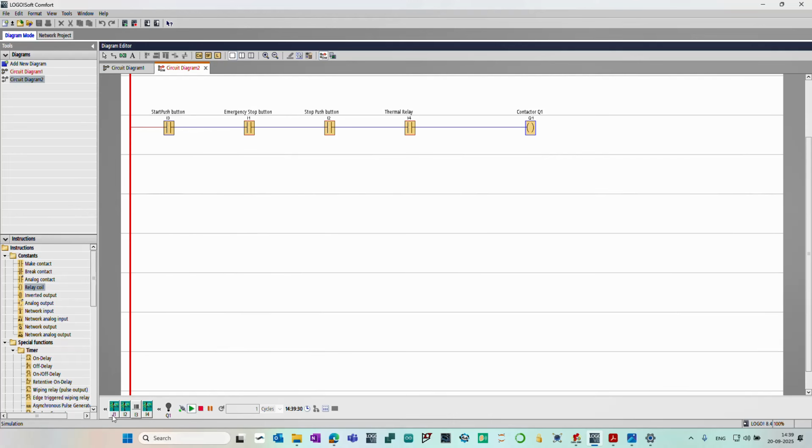If you see here I1, I2, or I4, they are normally closed contacts, and I have put them on the break, momentary break. So when I press them, it should break my contacts, or break all my wiring, the electricity through the wire. Only I3 is normally open momentary, so it will basically make my contact.